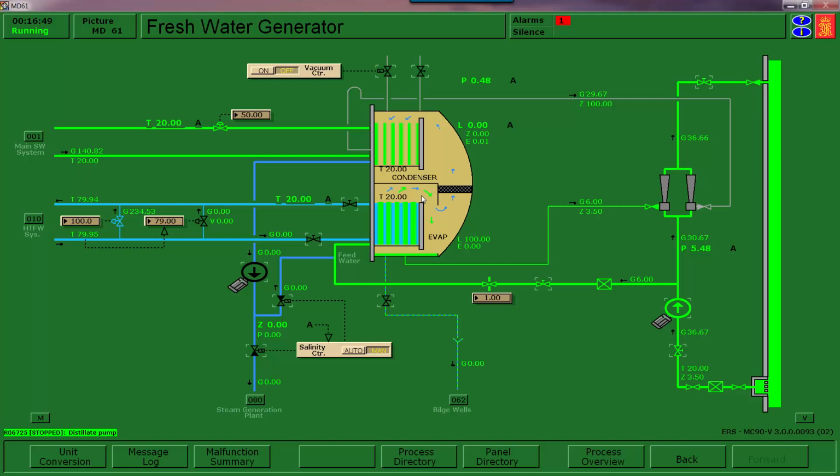You do the same exact thing on the Bear. It's just there's a little sight glass that you look for a half full, and then you start up the distillate pump. We're good on the vacuum, so I'm going to open the jacket water and go up to 25%.